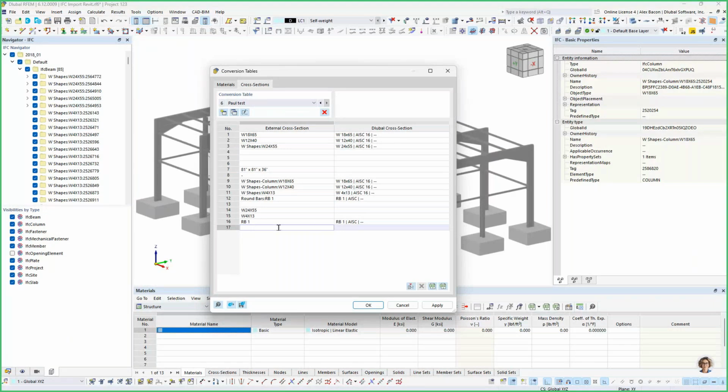With this cell here, you can simply use this graphical button to select the section or material name within the IFC properties. You can type it in manually. You can create an XML file, save it, and share that with colleagues. And you only have to do this once. So it's really quite simple to set up.